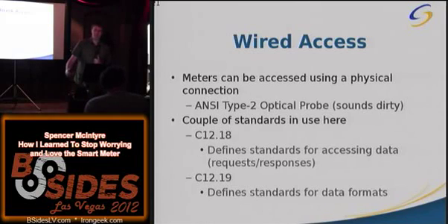once we are connected to the device, there's a couple of different standards that we have to look at, because that's the way that the devices are actually communicating to the system over the optical interface. There's the C12.18, which is defining the requests and responses, the formats of how the data is input and outputted, and then there's the C12.19 standard, which is actually two different versions. There's the 1997 and the 2008 C12.19 standards, I believe. And that is dictating and defining how the data is actually stored on the devices within the tables. So not how the data is being transmitted, but how the data is essentially at rest.